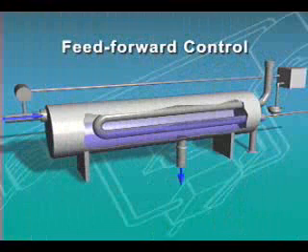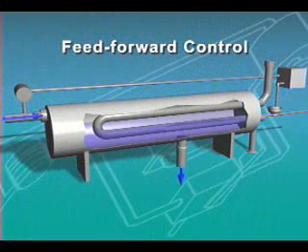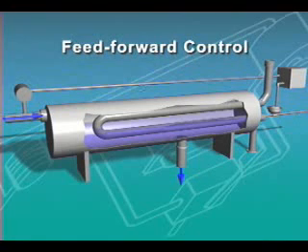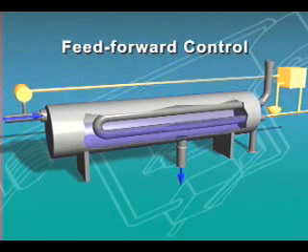In an automatic feed-forward control system, a temperature-sensing transmitter element would be installed in the water inlet, as opposed to the water outlet of the feedback system. If the temperature of the incoming water changes, a signal is detected by the measuring element, which is also a transmitter. The transmitter sends a signal to the controlling element, where it is then compared to the set point.